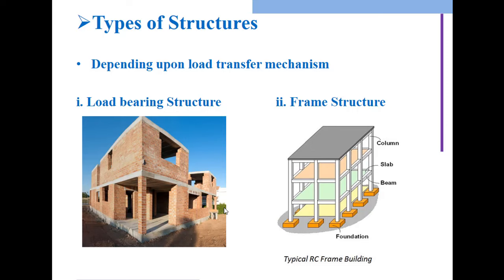But even though there is no, any kind of mechanical properties of the different steel are considered. Okay, so here in frame structure, if you consider the standard concrete, it should be from M25 to M55 grade. Okay, and their fck, which means characteristic compressive strength of a cube after 28 days in Newton per mm square, is 25 for M25. For M55 grade of concrete, this is M55, right?